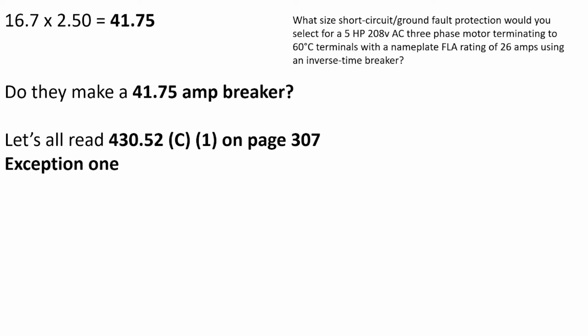I'm going to give you a little inside info. Next week we're going to size overload protection. You must use the next size down breaker. The next size up does not apply for overload protection, but we're going to cross that bridge next week. This week we're allowed to use the next size up rule.